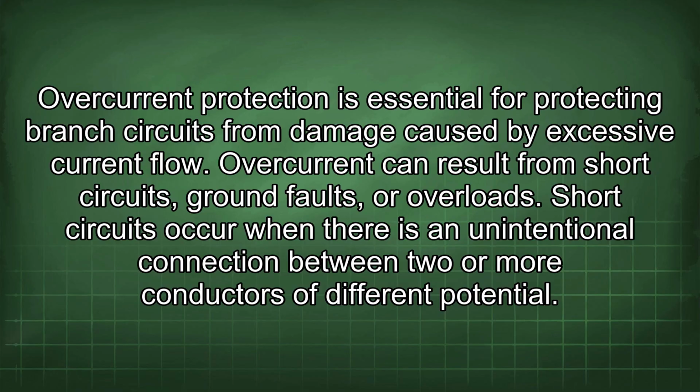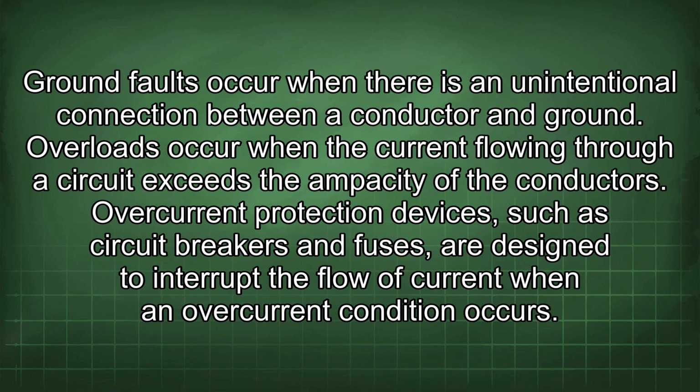Short circuits occur when there is an unintentional connection between two or more conductors of different potential. Ground faults occur when there is an unintentional connection between a conductor and ground. Overloads occur when the current flowing through a circuit exceeds the ampacity of the conductors.